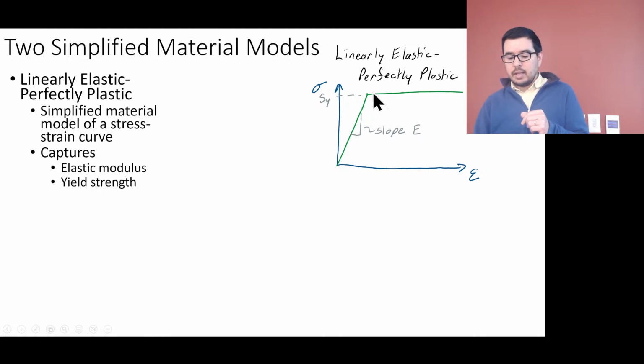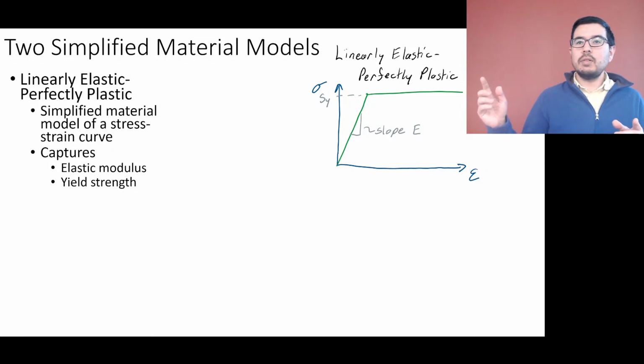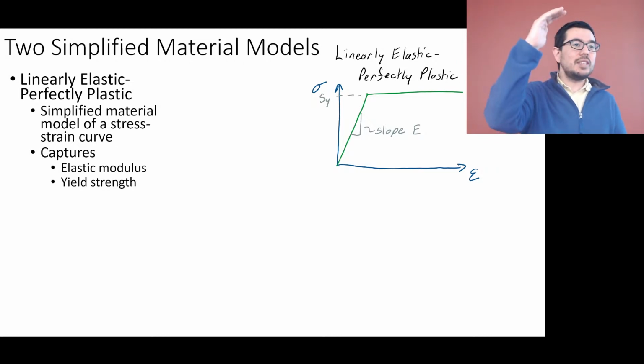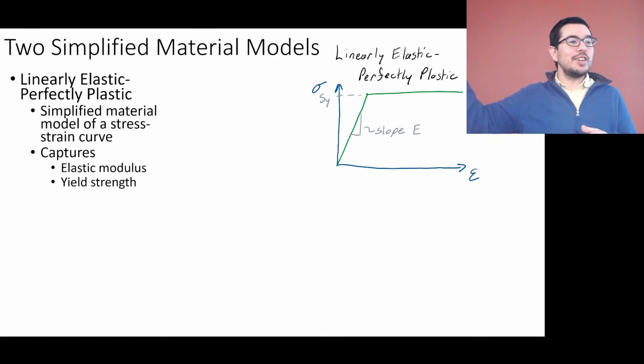Okay. And then physically, what does it kind of mean? If you just interpret what the graph says, you get strain, and do you have to increase the amount of stress you put into the material? No, that's kind of dangerous, right? It just kind of coasts. Essentially it says once you get to that plastic region and you're applying a certain amount of stress, you're just going to go until you break, okay?